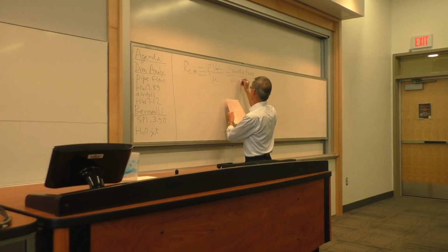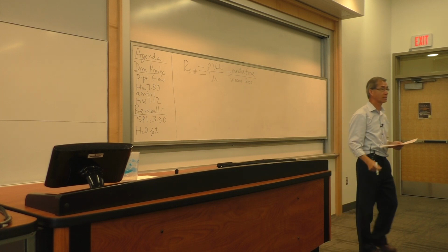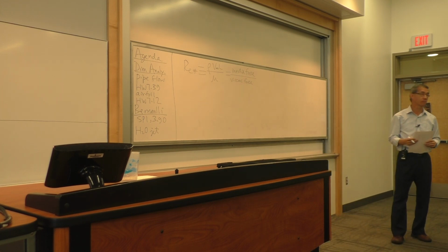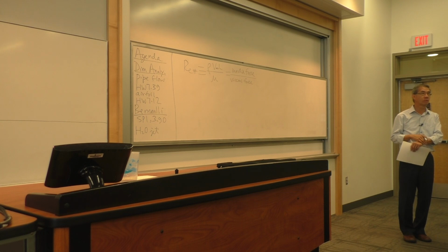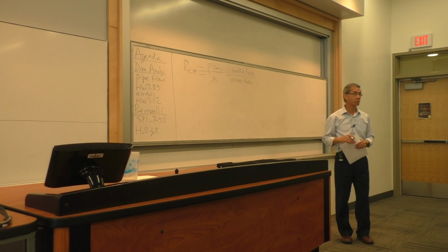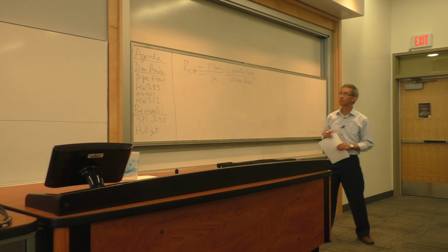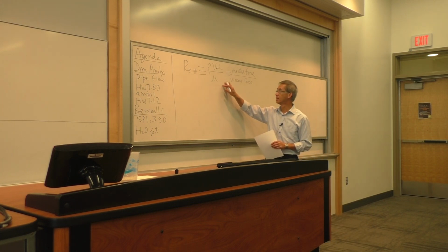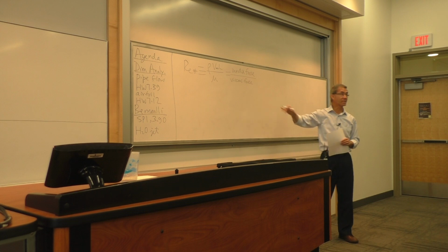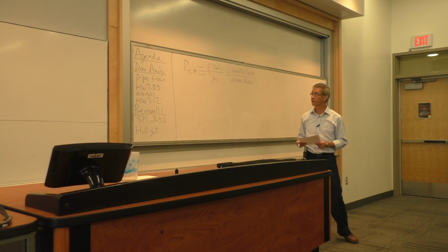It turns out if we work out the full equation of motion for viscous fluid, which we will do in the very last two weeks of the semester, resulting in the equation of motion including viscous effect, you find out that the Reynolds number will also appear in that equation. And when you compare the physics of what that viscosity in the denominator represents, it relates directly, not surprisingly, to the viscous forces. What is not clear is what we meant by rho v length scale and what I call an inertia effect.